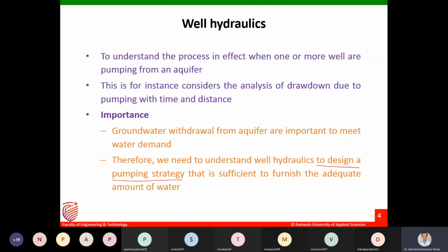There are myths among people that groundwater is an infinite source of water, but that's not true. Just like we store water in our overhead tank, the water gets stored in the groundwater, and it also has a limited quantity. If your recharge rate is lesser than your extraction rate, then what happens? Your groundwater starts getting exploited, the water level starts falling, and after some time you will not be able to extract a sufficient quantity of groundwater.